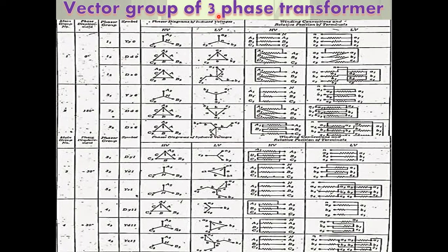The non-sinusoidal waveform can be considered to be made of the following: first, a constant term; a fundamental component having the same frequency as that of the original waveform; even harmonics such as second, fourth, etc.; and odd harmonics such as third, fifth, seventh, with sine and cosine terms. The frequency of the nth harmonic is n times the fundamental frequency. The RMS value of the nth harmonic is 1/n of the RMS value of the fundamental.